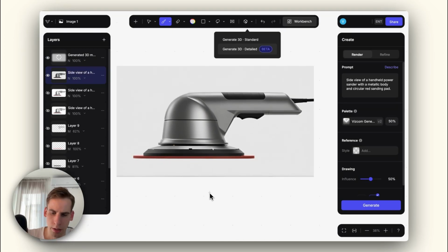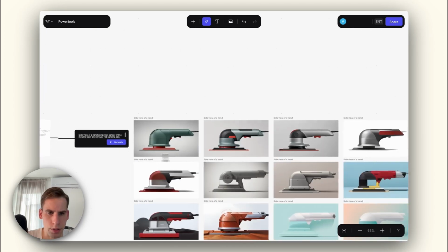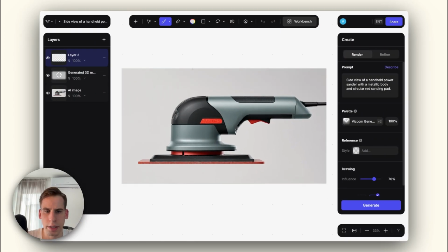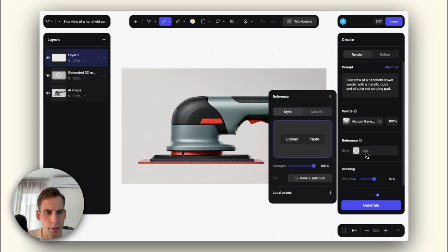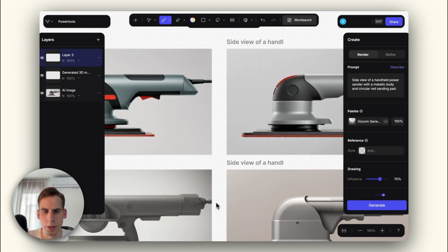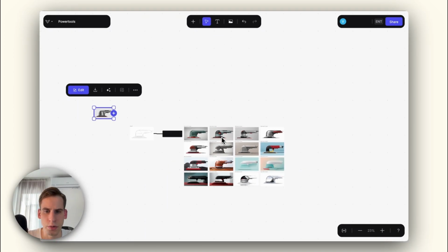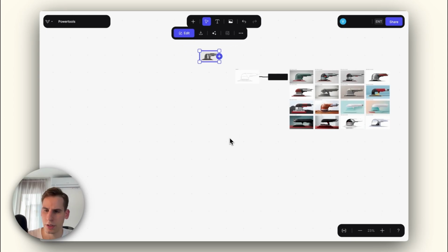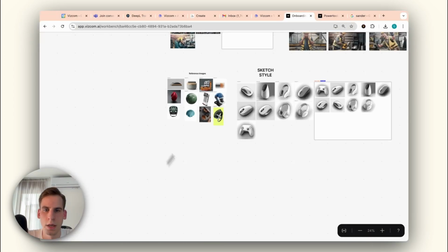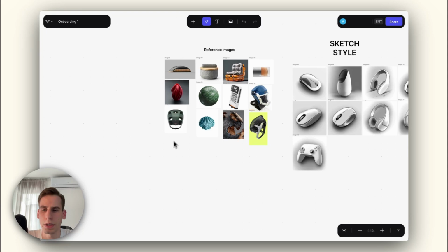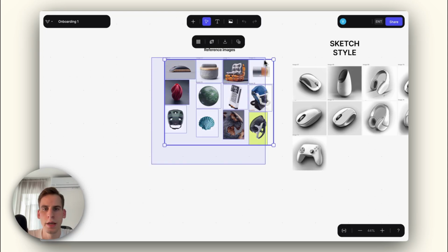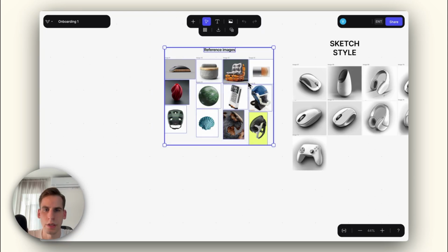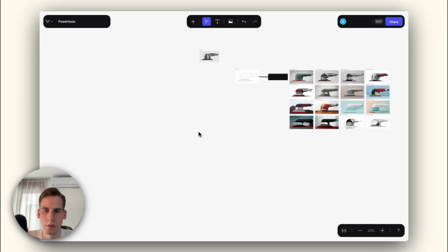In the meantime though, we can play around with reference images. I usually do that if I have a shape I'm satisfied with. I can now also explore the textures a bit more and some sort of other design inspiration. For that, we have the references, and I'm going to upload images here, but the way I usually upload my references is that I go outside to the workbench view, and here I just paste the images on the canvas. I usually have reference images already, so I can just visit a different workbench, copy these images. You can just Ctrl+C, Ctrl+V selected images through different workbenches.